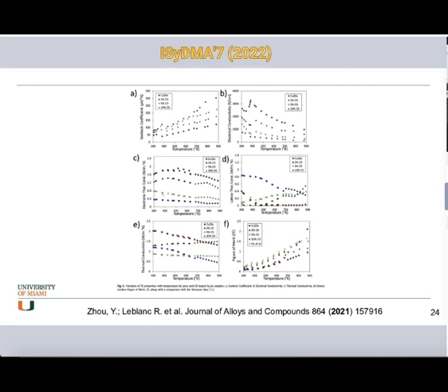If it is a high-value Seebeck coefficient, that means that you have a good figure of merit. If you have a thermal conductivity which is low, that helps to increase the figure of merit. So that's a main point. So this Seebeck coefficient increases with the inclusion of carbon dust.